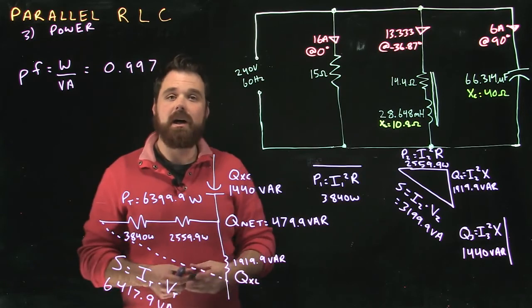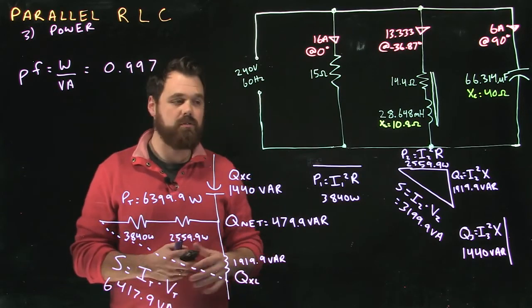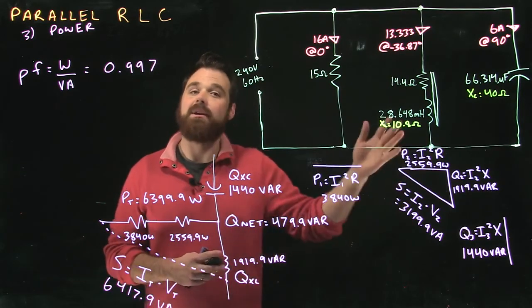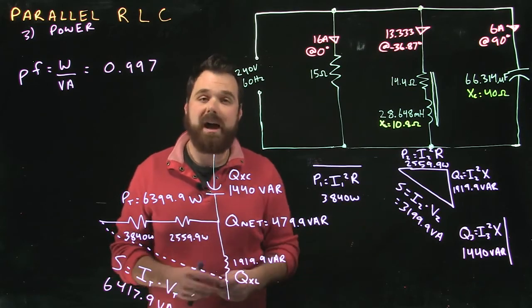Well, I hope that helps. It's really, really important to remember that you can add up watts and you can add up VARs, but you should never be adding up the VA.